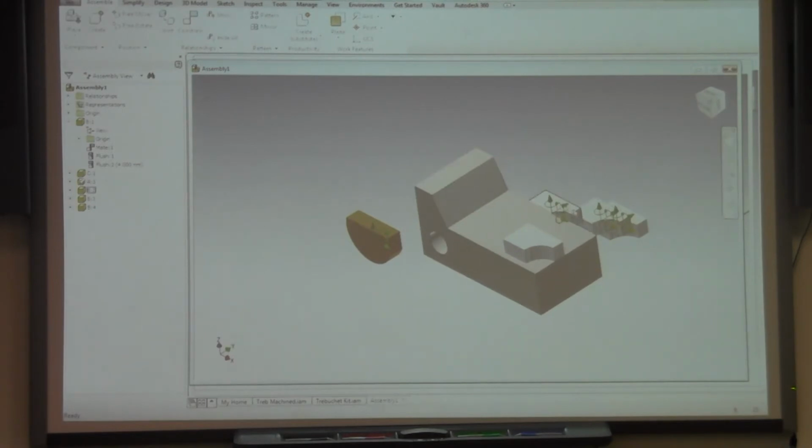You see, each copy comes with its own degrees of freedom. This piece right here does not have any more degrees of freedom symbols. Can you tell me why it might not have any more degrees of freedom symbols? It's glued down in every way possible. Absolutely. I glued it down face to face right here. It won't move off that plane. I did give it a 4 millimeter offset, but still, it's not going anywhere. 0 degrees of freedom.